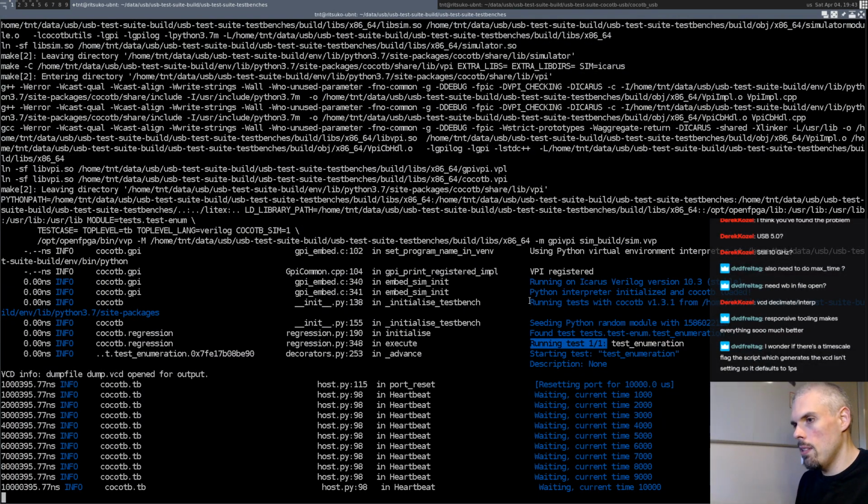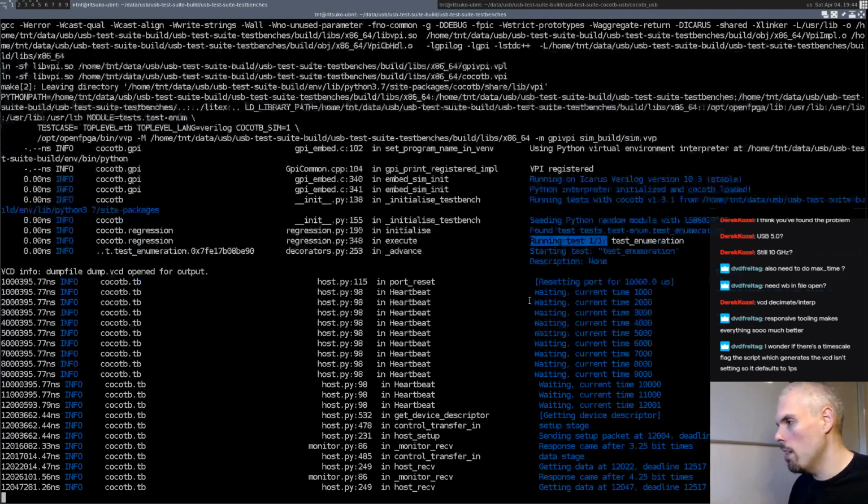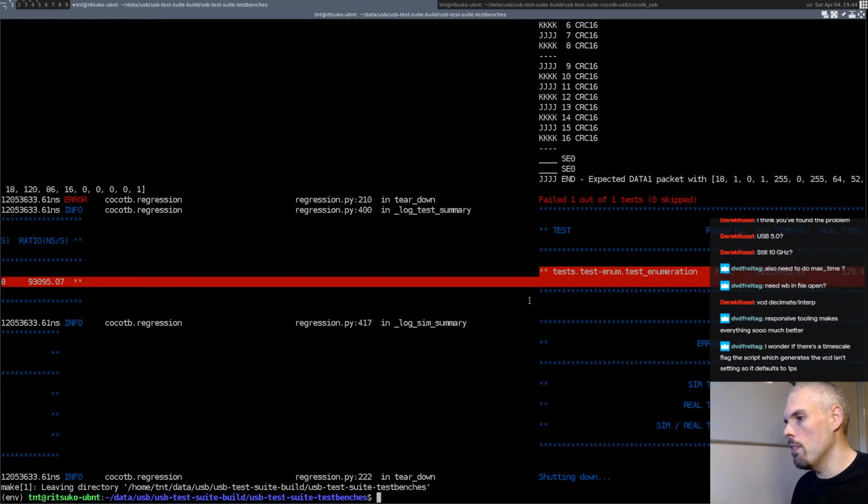One of the tests checks if the USB core works if the USB clock from the host and the USB clock from the device differ by 1,000 ppm or something, which the specs say should work. That means the resolution needed to simulate such small timing errors is relatively high. It needs a high resolution internally. When we display it, we don't really care, but during the simulation it might need that resolution.